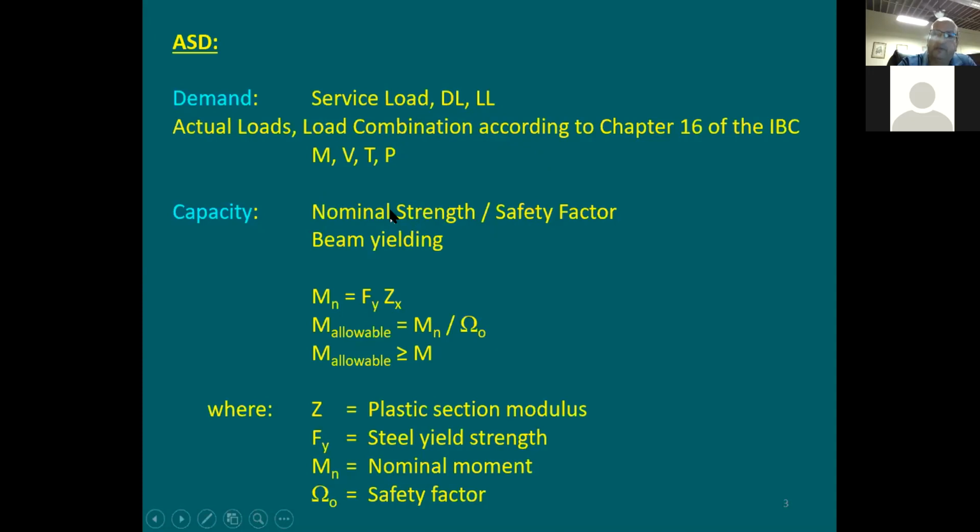So you don't want your design load to be approaching or to be close to the failure point. This is going to be bad because it means once I approach here, total design load, the building is going to be collapsing, or it's going to be cracking, or it's going to be yielding a lot. You don't want this to happen. So usually you need to take this nominal strength divided by a safety factor. This safety factor, let's say it ranges from 2 to 3, roughly. And with that, you're going to have some safety margin, as we call it.